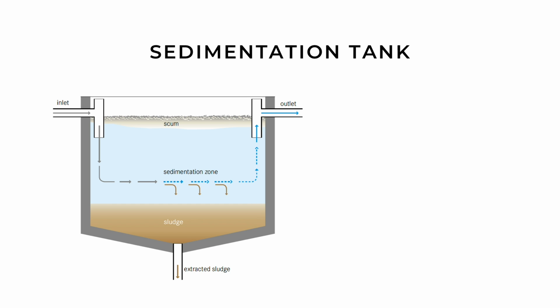In order to allow sedimentation, settlers need a hydraulic retention time of 1.5 to 2.5 hours. Sometimes you will find settlers with a higher retention time, for instance 8 hours. The construction of such units will not only cost more, but such high volumes will also cause organic degradation, which is not the objective of the primary treatment.